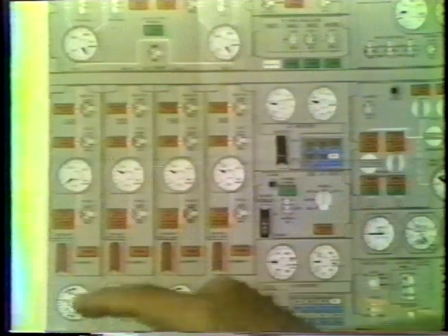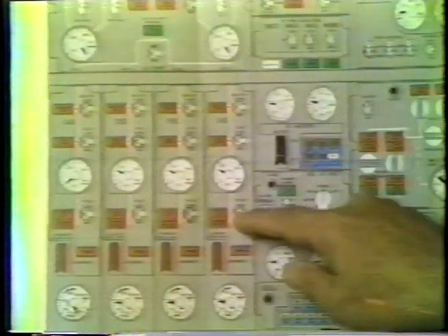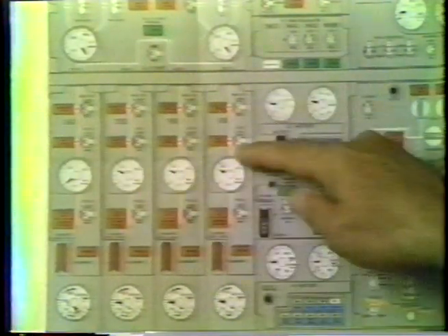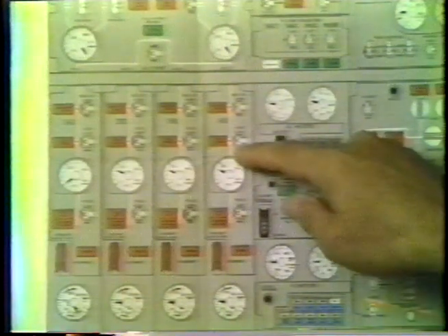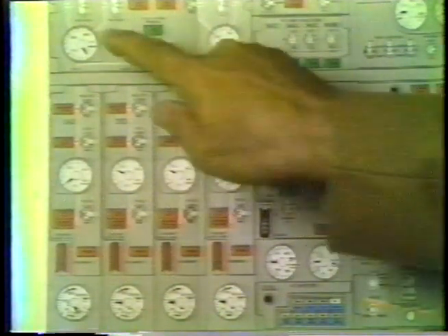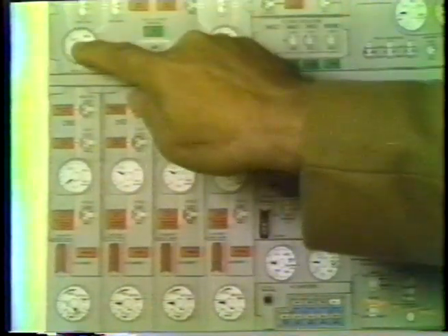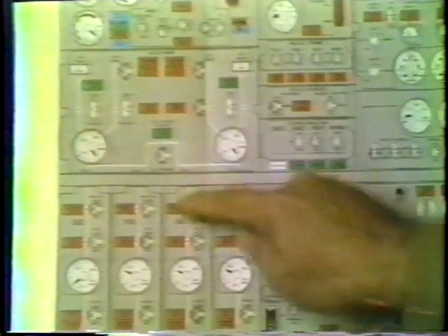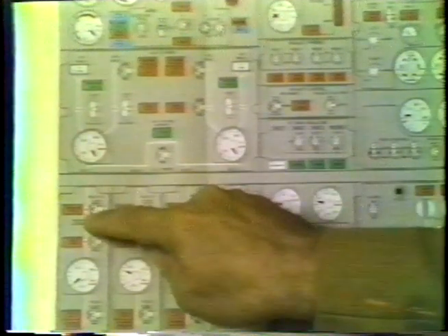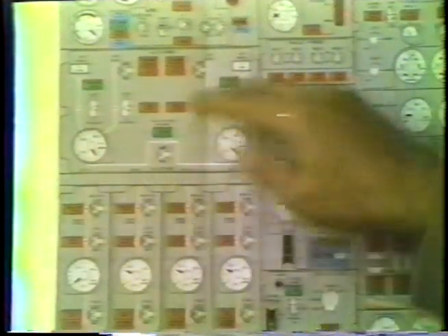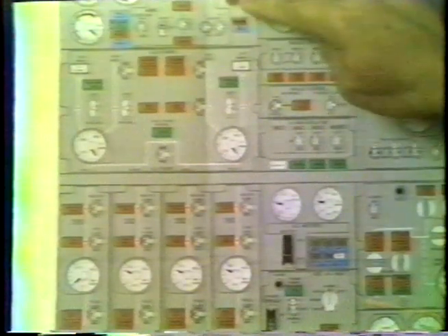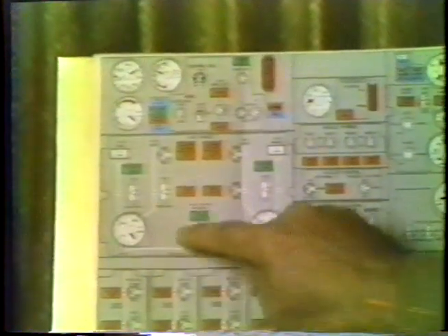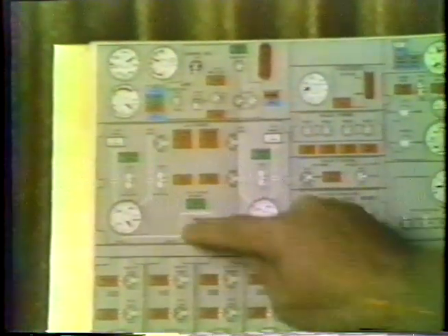Normally, prior to engine start, the fields are closed and the bus tie breakers are closed and the generator breakers are open. And power is coming into the aircraft either from ground power, external power number 1, through the tie bus into each of the 4 AC buses, or from the auxiliary power unit, APU, which comes in through the same tie bus to each of the 4 buses.